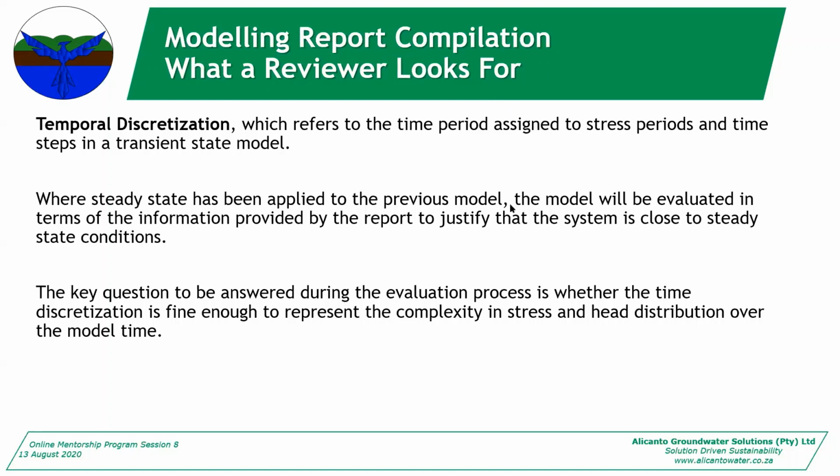Okay. So when you're choosing your stress period in a numerical model, the length of your stress period should be related to the change in stresses. So let's say, for example, I'm running a model for a mine, and the mining schedule progresses in monthly blocks. So every month there's a new block added to the mining schedule. So then my stress periods are going to be 1 month long, because in month 1, I'm going to have mining block 1. In month 2, I'm going to have mining block 1 and 2, which are stresses to the system because water is flowing into the mine and is being pumped out of the groundwater system.